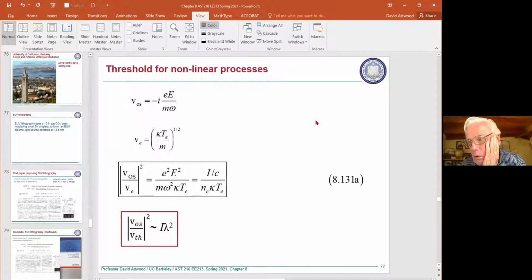And there was a breakthrough in Taiwan at the company TSMC, led by a guy named Tony Yen, who now lives here and works in the Bay Area. Up till that time, the EUV sources, the laser-produced plasma, the tin droplets with CO2, were producing average powers of like 10 watts. And it just wasn't enough. It was considered it would take a lot of work. One friend at Intel would just keep telling people, 10 watts is not going to do it.